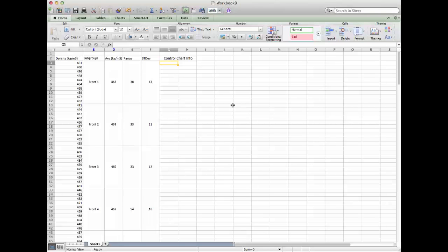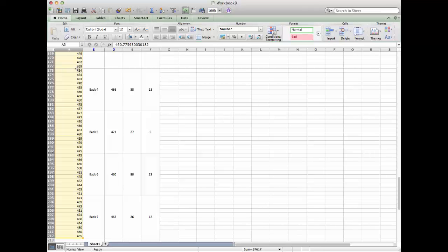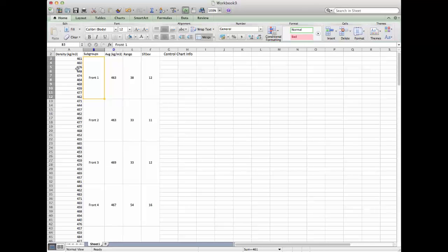The data used to calculate capability is going to be organized very similarly to data used in a control chart. And in fact, we're going to start off by creating a control chart from the data. Over on the left-hand side in column A, I have the density, we'll go back to our foam example from the car seat foam. I've got density listed in column A. For this specific example, I actually have 210 data points. In column B, I've listed those in subgroups.